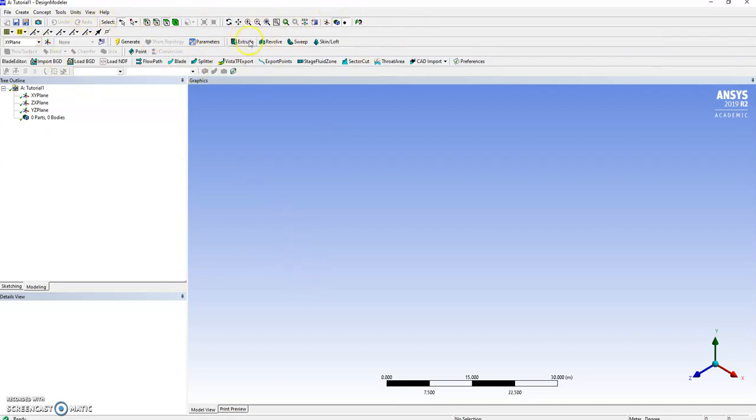We can recognize some things, I mean, extrude feature, but I will just make a shape, and you will learn to improve your use of that interface along the different tutorials. First thing though is usually to choose the right unit. So this one is in meter, and that's not going to help us, too big, so we are going to move it to millimeter.